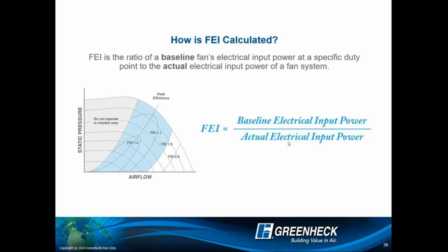All right, so all that said, I'm interested now. How does that tie into your system as well? The system effect could play with that a little bit if you think about it. Absolutely, you move around on where you're operating. If you have system effect, which we're moving into next, you can start pushing your point of operation into a less efficient or even a do-not-operate area real quick.